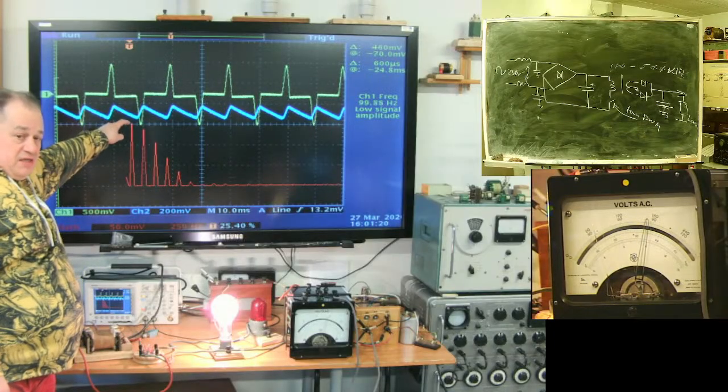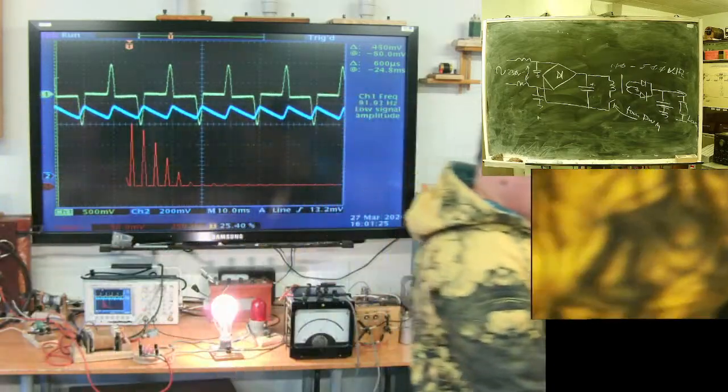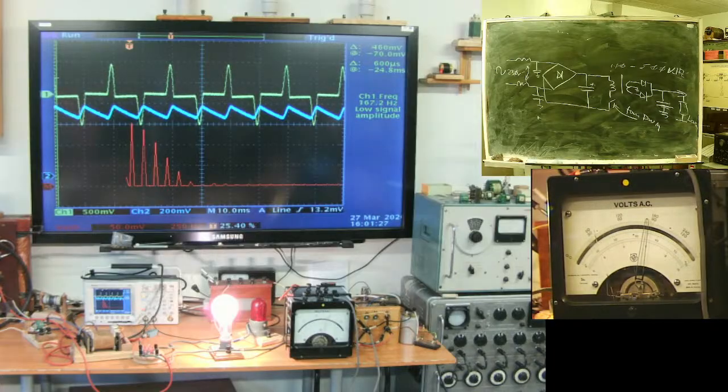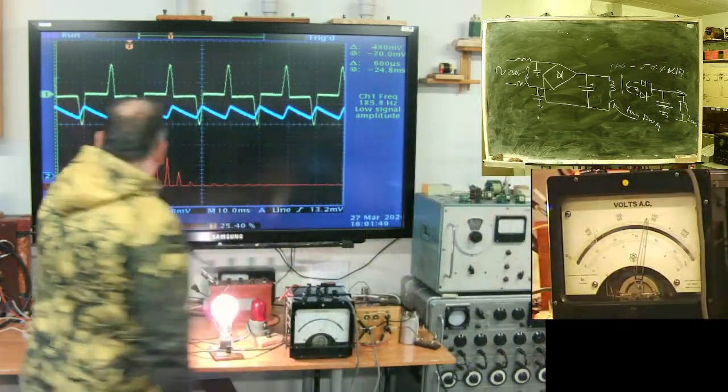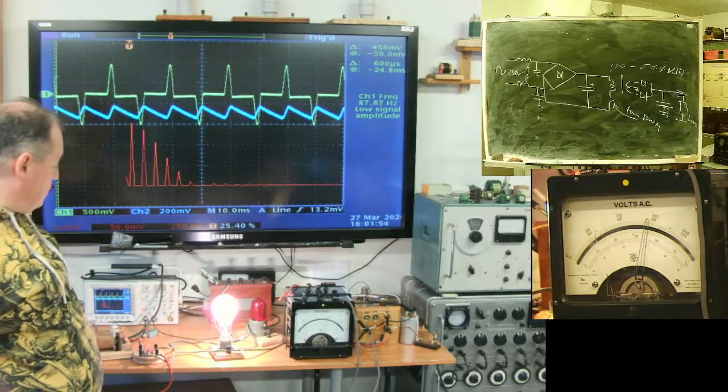Base frequency 50 Hz, 150, they are nearly equal. A huge amount of third harmonic flows through the network, and in the network neutral, in a polyphase network, where we have single phase loads all around, we will see triple this part flowing through our network.